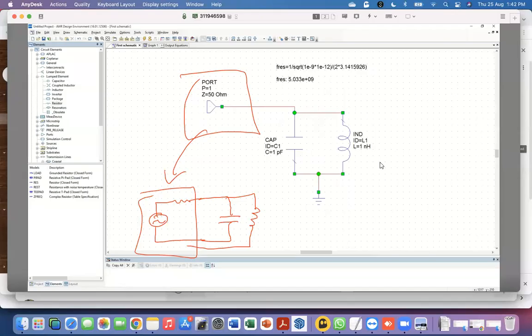So those voltages and currents won't be changing. But this is the caveat you have to remember, that scattering parameters are always in the steady state. You're not looking at the transient part. But the energy has to build up, and one can, of course, solve the differential equation, which is a very simple thing, and see these transients.